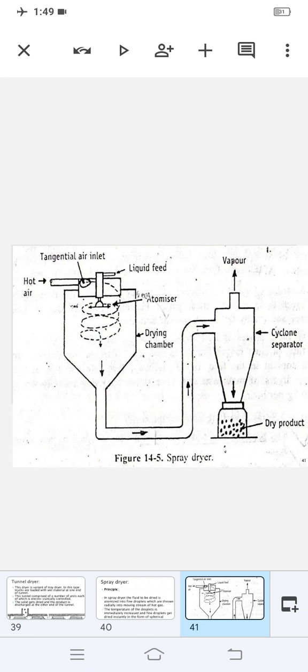As a result, the heat inside mounts up, which allows the liquid to evaporate at a faster rate. This causes a rise in the internal pressure, and it causes the droplets to swell. As the shell's thickness decreases, the permeability for the vapor also increases. If the shell is neither elastic nor permeable, it ruptures and the internal pressure escapes.